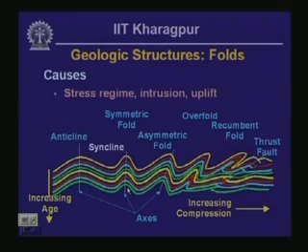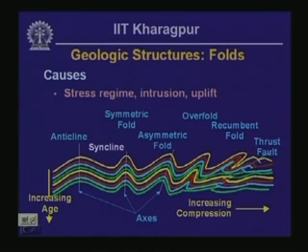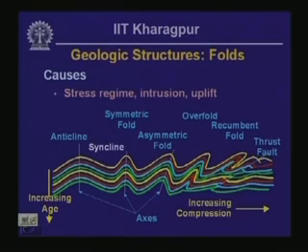Okay. Now we can describe different types of geometry of geologic units. We now want to get into different types of geologic structures that you are likely to encounter if you work as an engineering geologist. The first type of geologic structure that we consider here is called folds. Now the sketch that is shown there schematically presents a series of folds. In this case we are looking at a vertical slice through a bedrock, and generally, as we go deeper, the age of the bedrock increases.